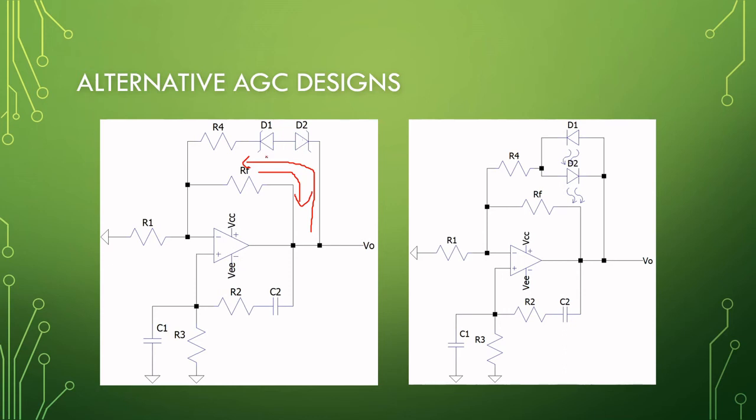So this is a quite easy way to limit the output, but sometimes you are limited to the amount of Zener voltages that is available and costs and whatnot. So choosing these two the same Zeners, you will have a limiting which is symmetrical. Next implementation is to take some LEDs.